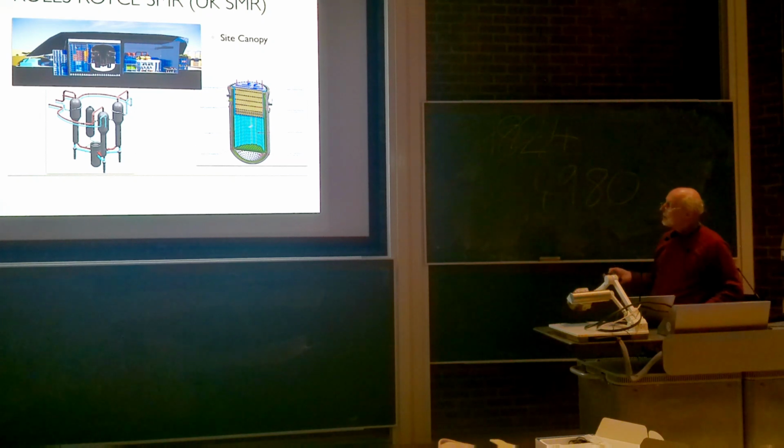To refuel a PWR, you have to unbolt the top of the pressure vessel, take out all the gubbins that's above the core, and then, well, either lift out the entire pressure vessel intact and replace it with another one, or if you're keeping the pressure vessel, put a new core in and put all the other gubbins back. So it's quite an event to refuel a PWR. And I guess that's why generally people want 2 reactors on the site, so that when it comes time of refueling, one of them can be shut down to refuel.